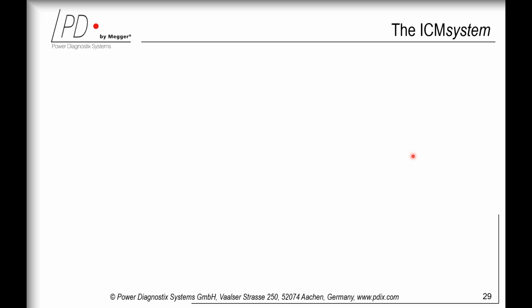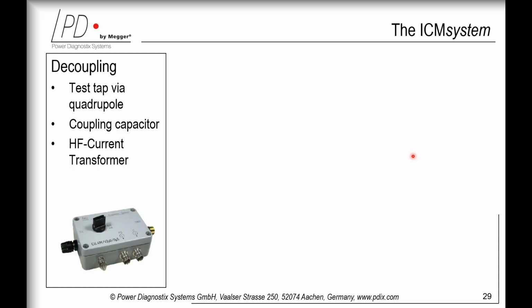After presentation of the instrument, we will now come to the measurement chain. The measurement chain looks like the following. The standard decoupling unit uses either a measuring impedance connected to a bushing test tap or a coupling capacitor. However, there are cases where a current transformer may also aid the conventional PD testing, either by being used for gating or for decoupling the neutral or similar.